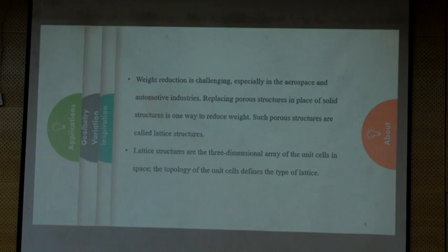The Young's modulus need not be the same as the aluminum material because that is not a standard method. The standard method is the tensile specimen. So the Young's modulus is varying. The good thing is we are using this in bones and all those things because that Young's modulus should match the bone modulus, right? Because like that we are varying the properties and we can finalize it, which is good actually. There is research going on in lattice structures, mainly in the biomedical bone. We will take bone as an example and see how we design it with the lattice structure in nTop. Okay.